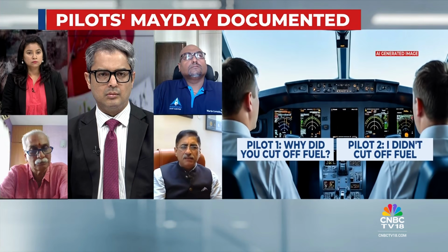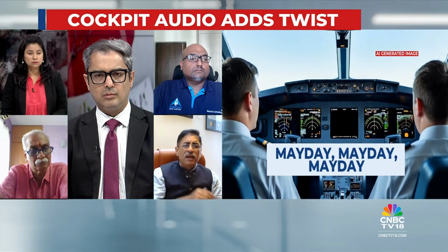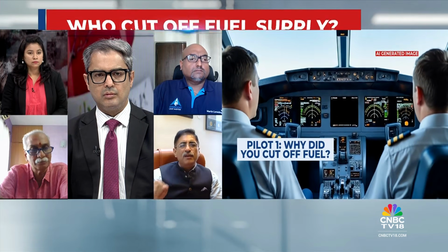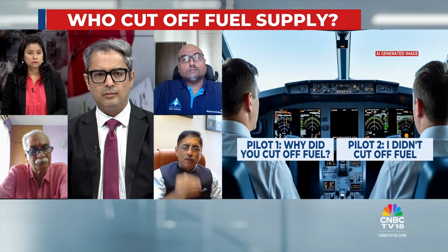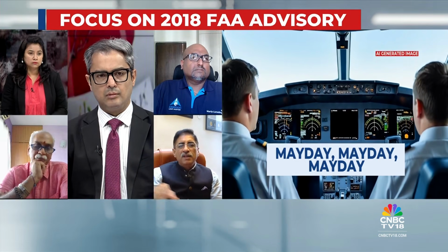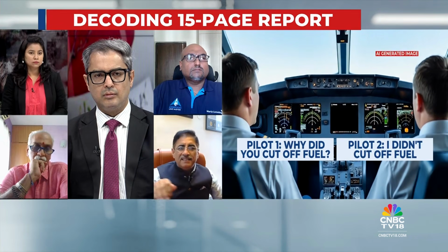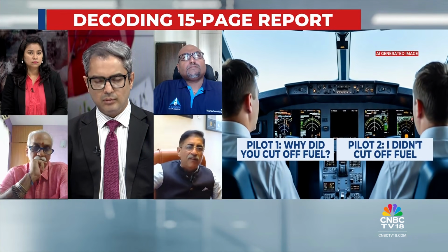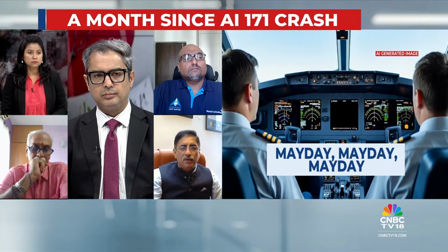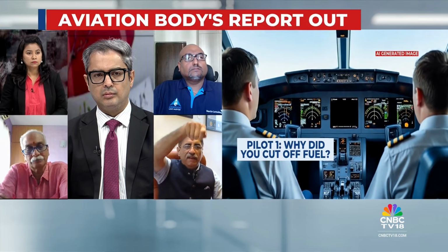And as the action takes, both are seasoned pilots, and I was speaking to Anand a little while ago, that there is no action in a multi-crew cockpit which one person can do by himself or herself. It is always challenge and response. So one pilot will say, moving the fuel control cutoff switch to off. The other one will say, okay. And he looks. This is not a run-of-the-mill switch that goes down with one flick. These are spring-loaded switches in latches. So these have to be physically moved out of the gate, lifted and brought down. It is not inadvertent touching.